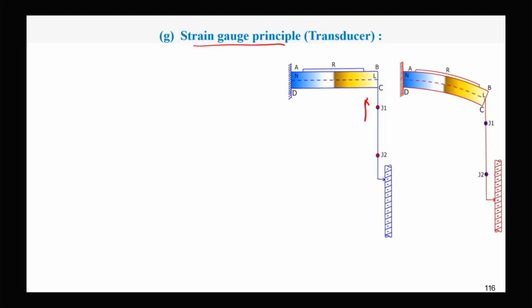So that's why we consider this principle as constant rate of elongation, because this lower jaw is moving at a constant rate. Although there will be deflection, still we don't consider this principle as constant rate of traverse.